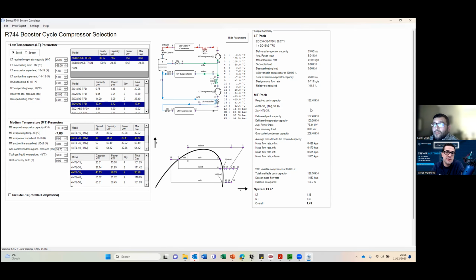Just like when you're sizing and selecting compressors, I highly recommend you go out and get into these softwares. They're free. These manufacturers are doing a great job providing all this software for free for you to go and check them out, get into their documents, get into their technical papers and look at how they run. Can they use a drive on them? What's the range? Just playing around with this, I saw a few things, even on the Bitzer software, just moving it up and down, seeing that frequency change depending on the compressor will make a big deal in those selections.